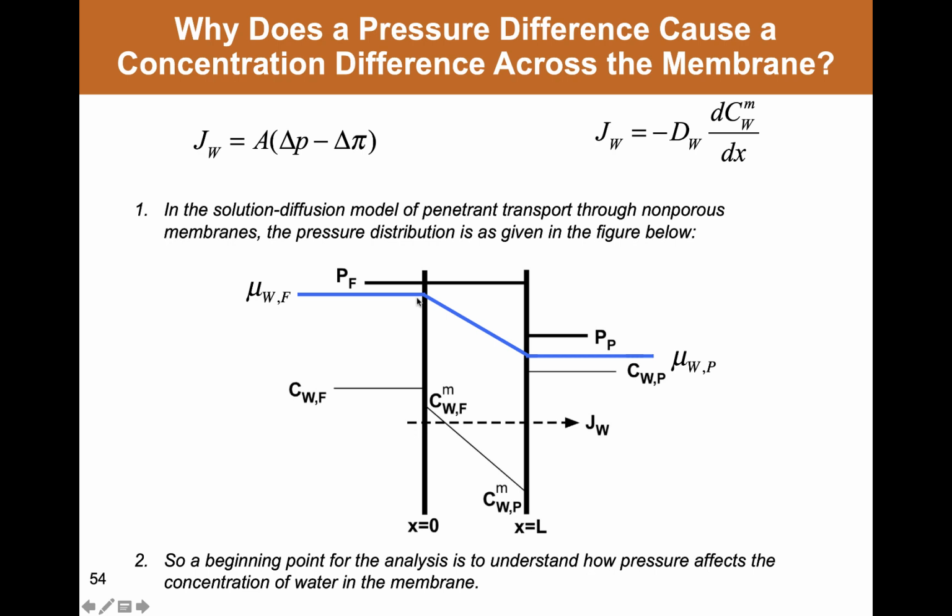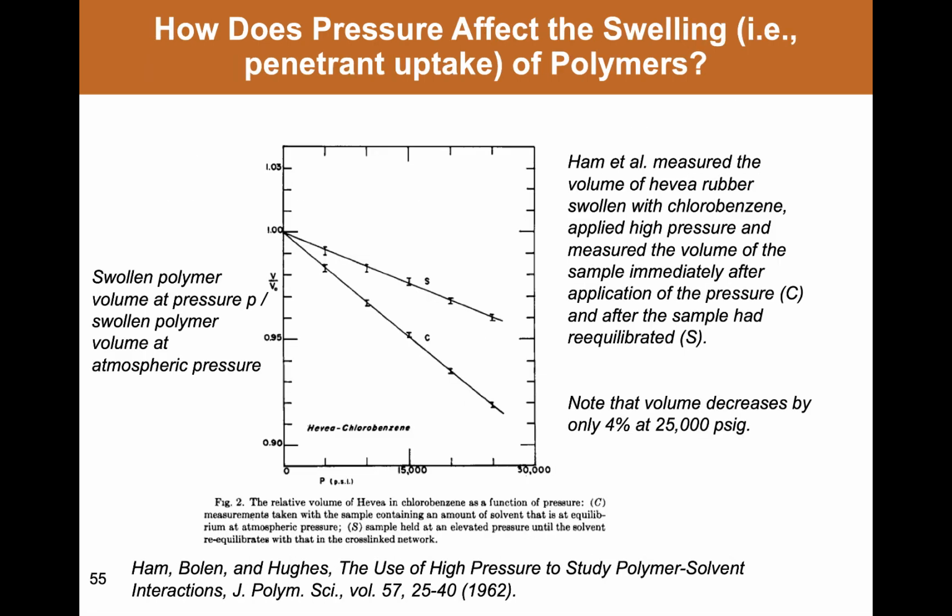This will be the key to the analysis, the thermodynamic part of the analysis at least: this continuity or equality of chemical potential of penetrant in the water next to the membrane and penetrant dissolved in the polymer at that water membrane interface, or solvent membrane interface in the case of the organic liquids.